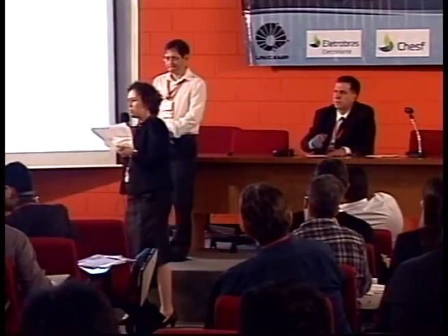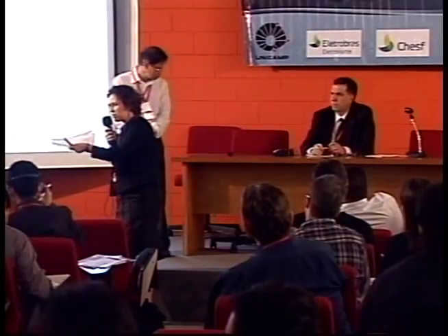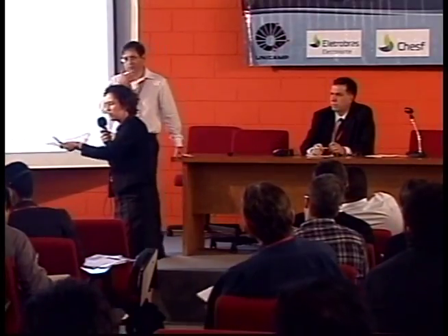And our idea is to conduct the test during a day where we don't have a high probability of rain. But we're talking about 2,600 kilometers, so a single-phase fault can happen. A three-phase fault is very unlikely to happen during the test. It would be a lot of bad luck for it to happen, but not for the single-phase one. So in reality, when we verified the stress of the three-phase fault, it's more just to complement our task list, because we really do not expect it to happen. After that, of course, the protection needs to be for all types of fault. So that's why we have kept the surge arresters, because during the test they will be there.